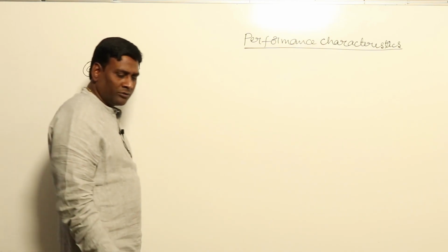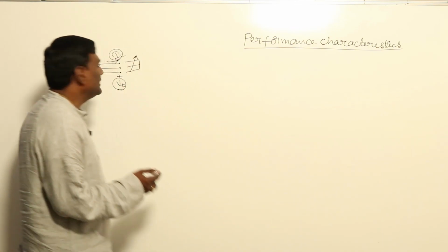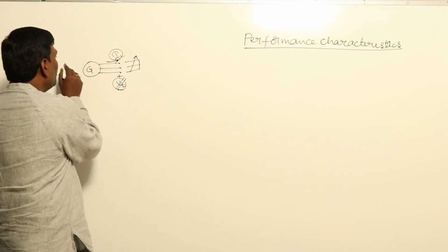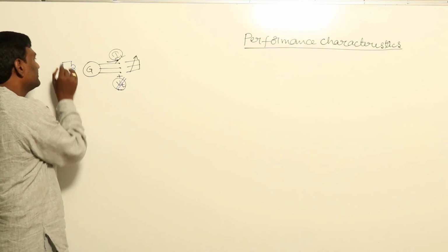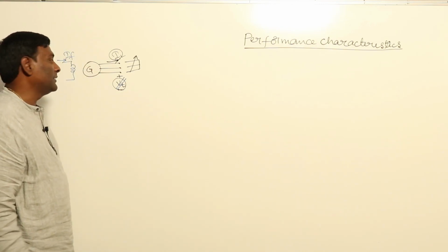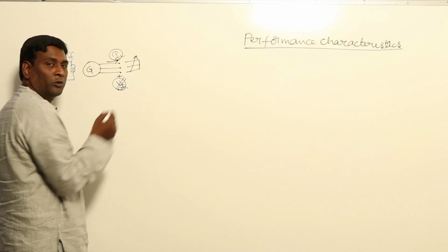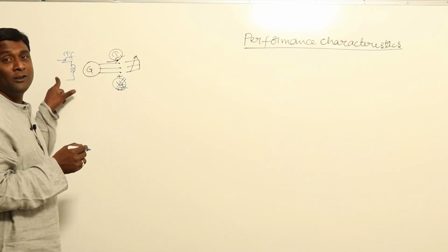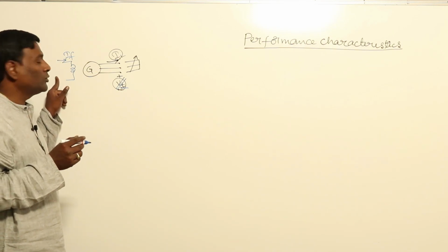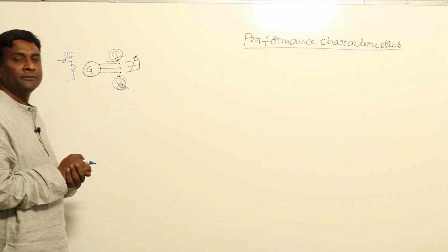Now let us think like an engineer. In order to maintain terminal voltage constant, how my field current If should be varied, which is internal to the machine and will be maintained by the operating engineer. So that is the internal characteristic.